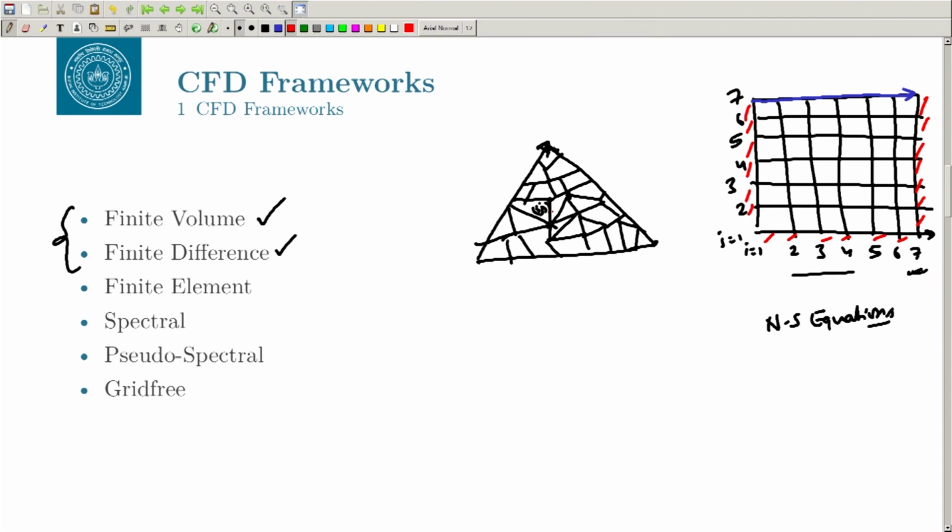It is very difficult to define because this grid is unstructured, in the sense that there is no proper structure present there. All you know that okay, I have got this cell, okay, let us say this is a cell, and for every cell edge face I have got the left cell and right cell, okay. This is left cell and right cell, left cell and right cell, right, and this is true for every cell. You can take this cell here also, you have this here, both the sides, and so on and so forth, right. So, for every edge, okay, where the flux may be going, you know what is the left cell, what is the right cell, and this is my edge of the cell, right.